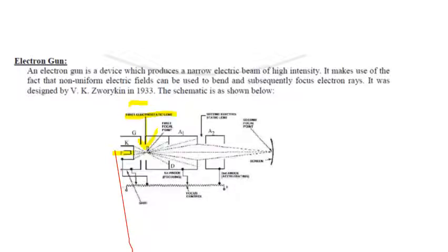Due to this, the electrons get focused here at P. We did the same in optical arrangements also. First we focus our light, then refocus again, because a basic property of good focusing is that the source must be a point. And the cathode cannot be treated as a point. So first we create the point P. Then from here we pass.